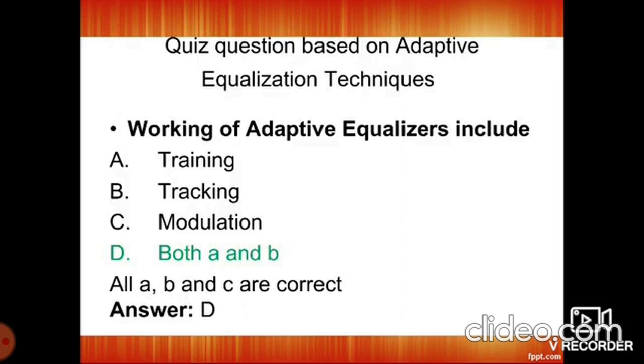So adaptive equalizers are used in telephone channels. The telephone channel is made up of individual links. The distortion for a telephone network depends upon the transmission characteristics of individual links and the number of links in the connection. Hence, a fixed pair of transmit and receive filters will not solve the equalization problem completely. The transmission characteristics of the channel keep on changing. Therefore, adaptive equalization is necessary for the transmission channel.